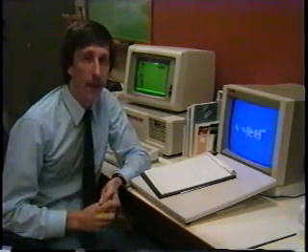Well, we're done with the flow test, and here I am back at the computer terminal again. Now's the time where we have the opportunity to do a lot more with the results of the hydrant flow test than simply plug them into an equation and predict the discharge at 20 psi. The first thing you need to do is to save the results. It doesn't really matter if you write on a piece of paper or store them on the computer, but nowadays there are some nice features in computer databases and spreadsheets where you can take the results and store them year after year, and then you can go back and look at the results. How did they change with time? What are these changes in time telling me about what's happening to the distribution system?